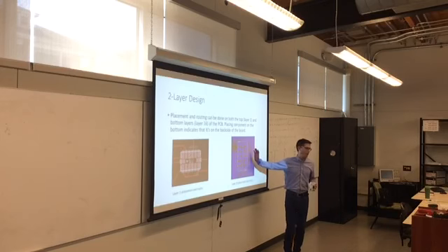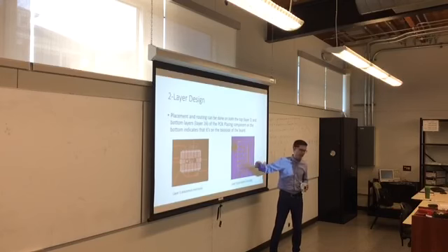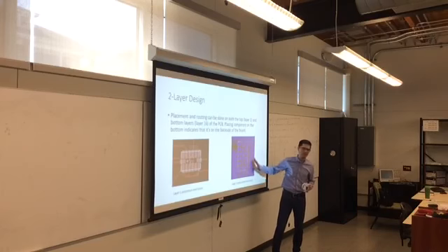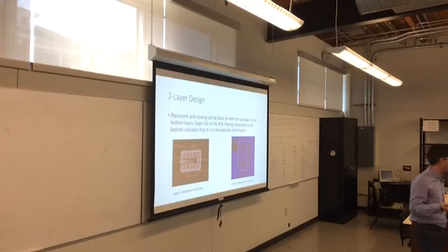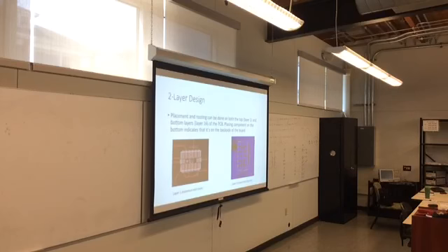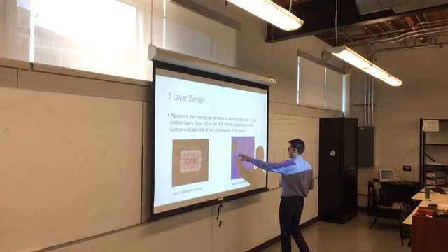This is the back or the bottom of the board. So if you wanted to put the chip on the bottom, it can go on the back side of the board. There is routing done in this layer, and the remainder of this layer you see is solid blue because that all gets connected to ground. So usually the bottom layer, you can route on it, and then everywhere else in that layer that's not connected, it gets filled in with a copper pour, and that becomes ground. And it isolates components, but it also gives you lots of ground connections.